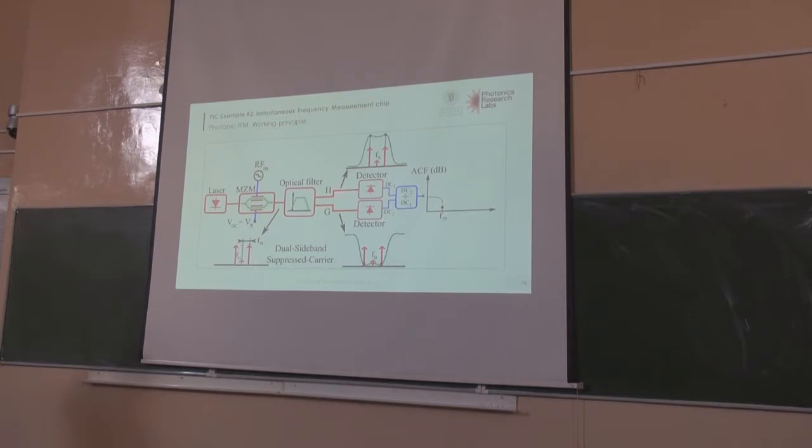Okay? Here what you are taking is the DC ratio between the detection of this and this. Okay? So what happens is that the frequency changes, the amplitude value of the subbands changes, and the ratio between them changes. Okay? So basically, what you get is a function which is called amplitude comparison function, which depends on the RF frequency.